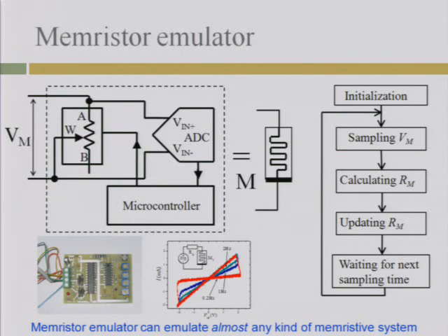The main element in this emulator is a digital potentiometer, and the wiper of the potentiometer and one of the electrodes serve as the external connection of the Mem-capacitor.